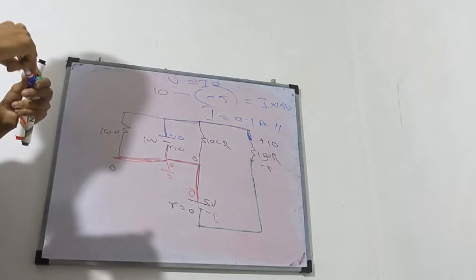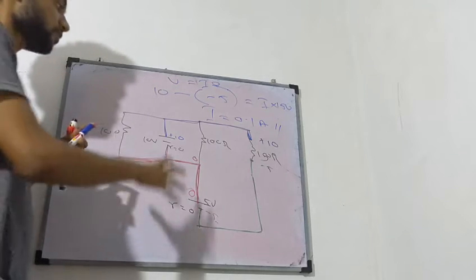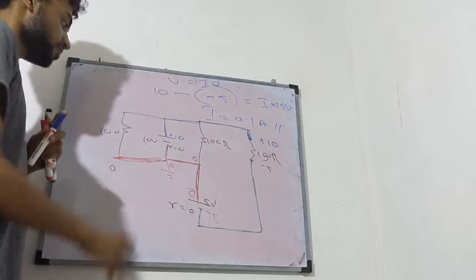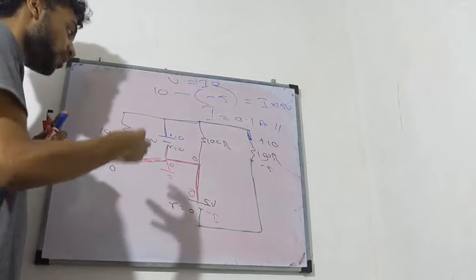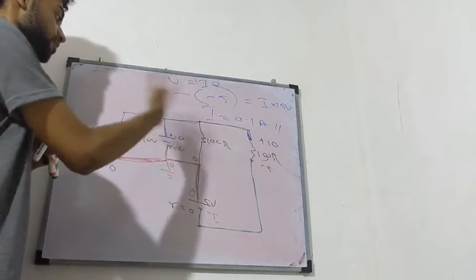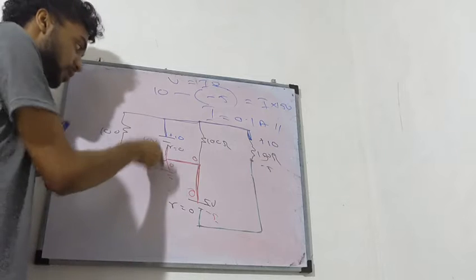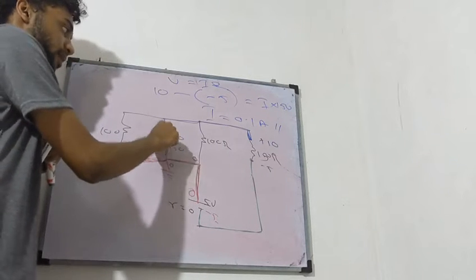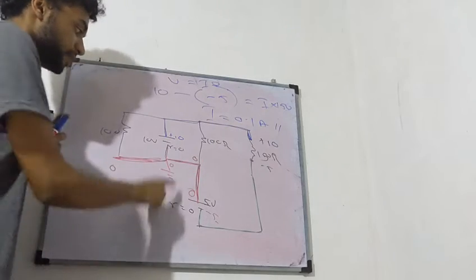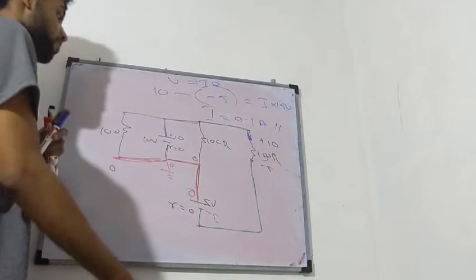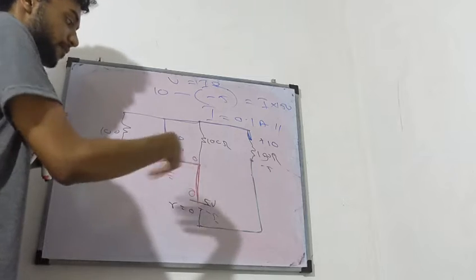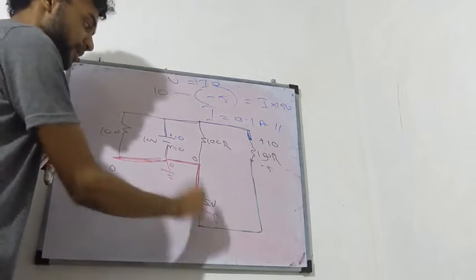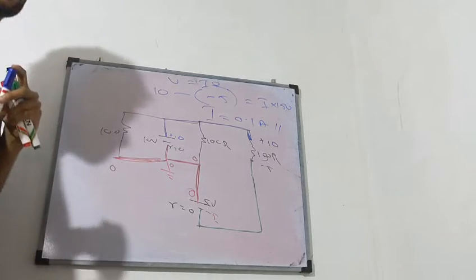So you can note these particular points when you're solving these kind of questions. So understanding that you can ground at a certain point, and then how you can get potentials at other points. Now, for example, I grounded this terminal of the battery, and then this becomes plus 10. So the plus 10 continues throughout, and then it's 0 here, and therefore I have to have the potential difference of 5 volts. Therefore, if 0 here, it should be minus 5. I hope you understood this.